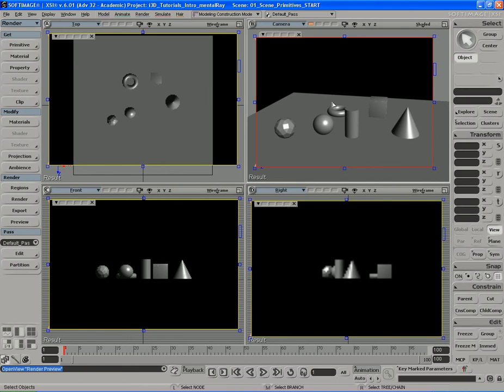I could do essentially whatever I want with these render regions. So this allows us to go ahead and change the options for the render region tool independently of each viewport. Now the guideline is that you're limited to one render region per viewport. So we have 4 viewports, so we can have a maximum of 4 render regions, 1 per viewport. So that's the little restriction that you gotta abide by.